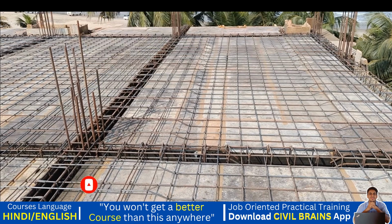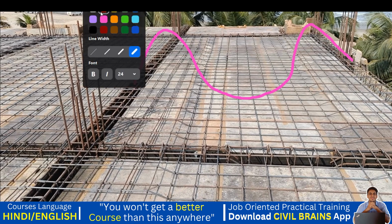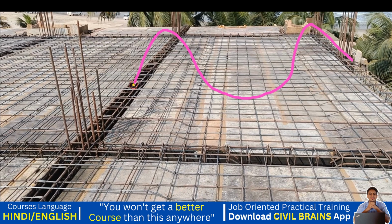Here, this is my negative bending moment, this is my positive bending moment, and from here again negative bending moment will happen. I'll change that with a different color. This negative, I'll go with this yellow color. This is negative. Again from here also negative is going to happen. And this is my positive, the one which is pink in color.